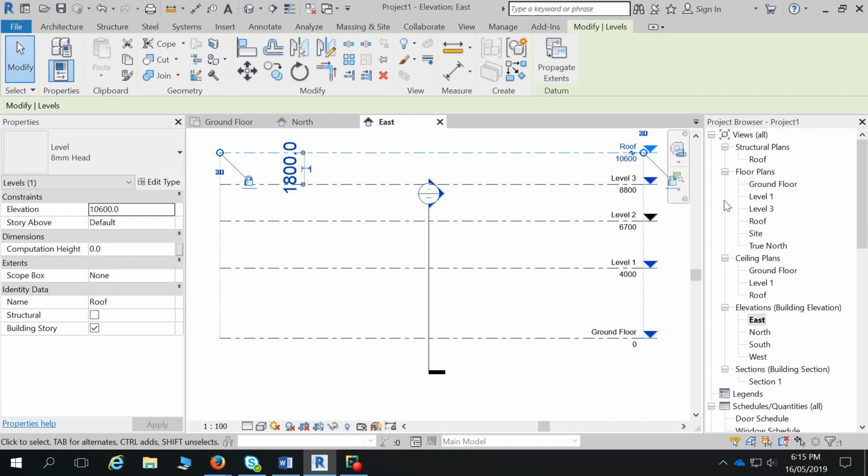I tend to say no, because your project browser can get pretty confusing. Ideally, if I was starting a job from scratch, I would have like 00, 01, 02, so it flowed logically in my project browser, but on my floor plan, I don't want to have 00, 01, 02, 03. You want to have just like ground floor finished floor level, ground floor finished ceiling level.